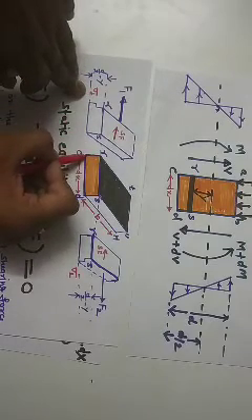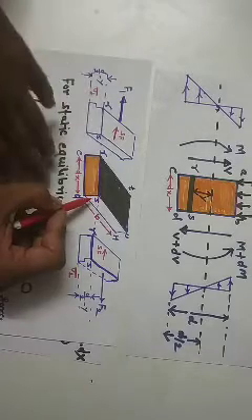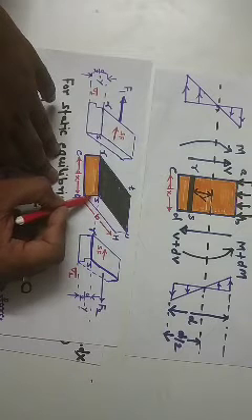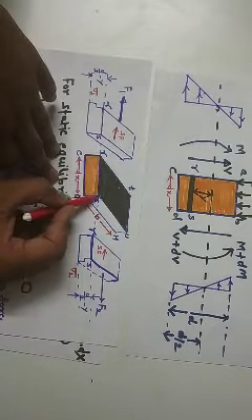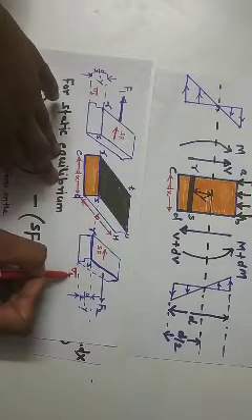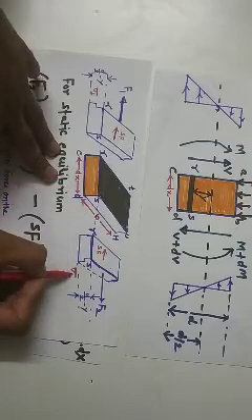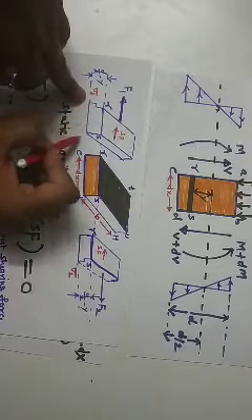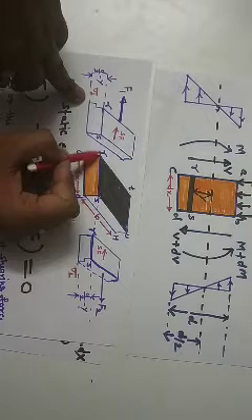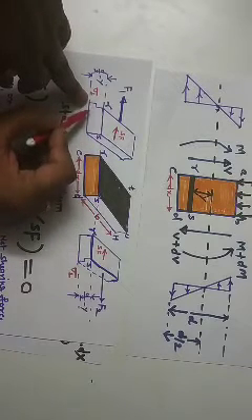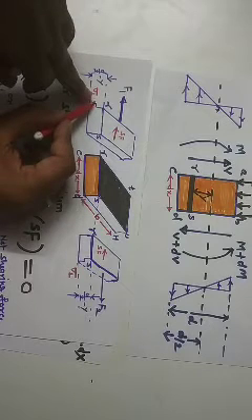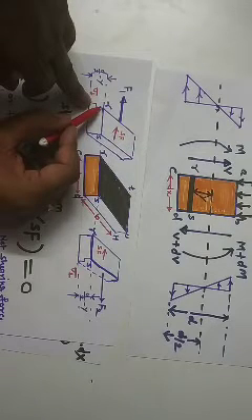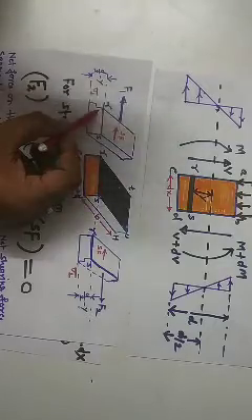At this portion RC, the bending stress is sigma 1, and due to the bending moment M plus dM, the bending stress set up in the beam at this portion DS is sigma 2. Due to these two bending stresses, what happened? There is sliding of layers, right? Here we are watching from C to R. When we are moving from C to R, the layer close to C is extended, and the layer away from C is less extended, right? That means there is sliding between the layers.